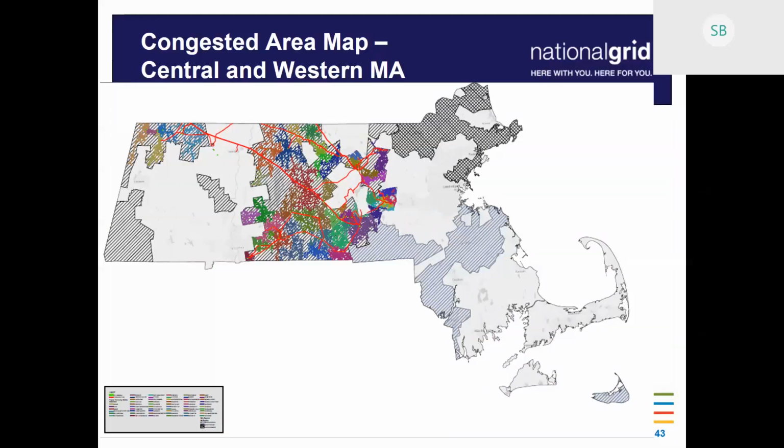That carries a lot of complication, from actually getting the substations built to physically finding the location for where to put them. It also requires a reconfiguration of pretty much all the feeders in that area, because we're not building express lines or express subs to serve DG. It's serving the area in total, both the load and the DG, so we've got to reconfigure everything.